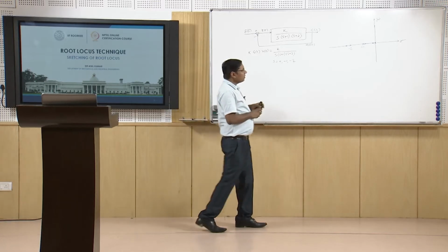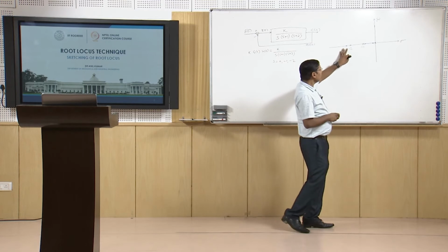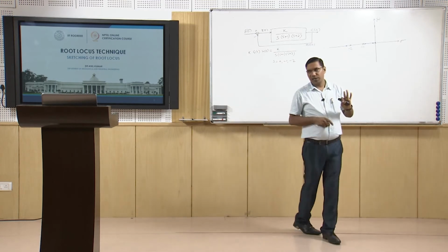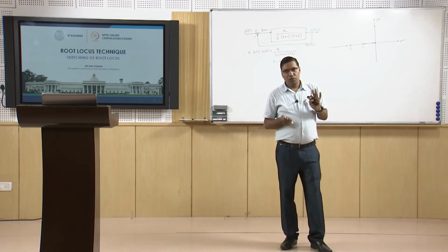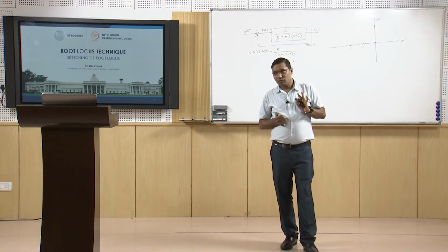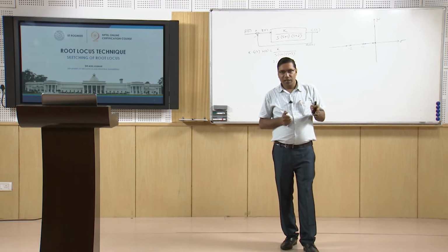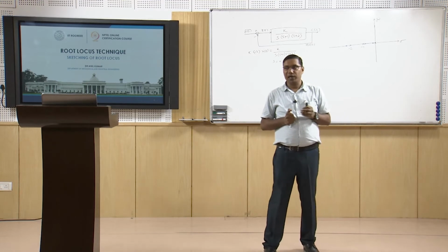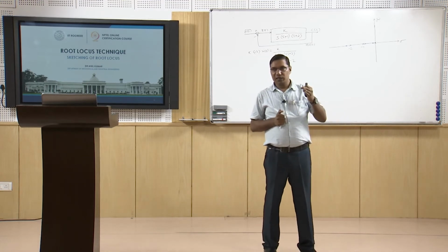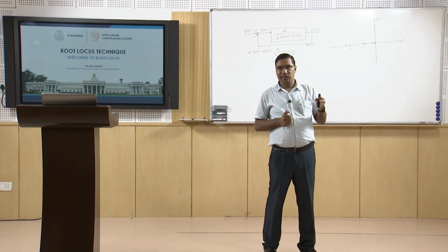So we know that these root locus branches are starting and going to infinity. So rule number 5 we have to apply, and we find, if they are going to infinity, what asymptote they will follow as a straight line, and at what point that line will cut the real axis.